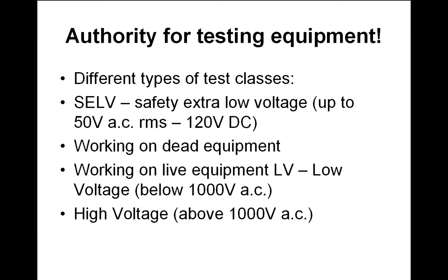I think we talked about it last time a little bit. So SELV is supposed to be safe. If you get a shock, it's unlikely to kill you. At 50 volts, you will feel it, but unless your heart is in a really bad way, it is unlikely to cause fibrillation.